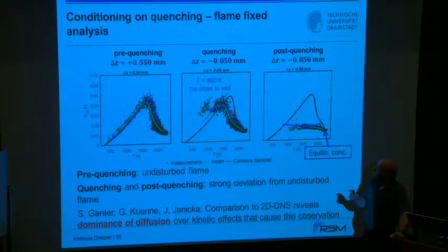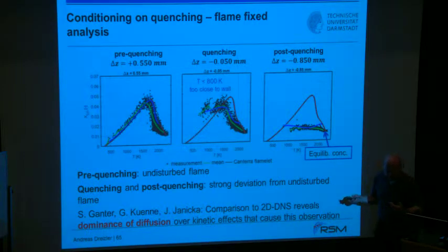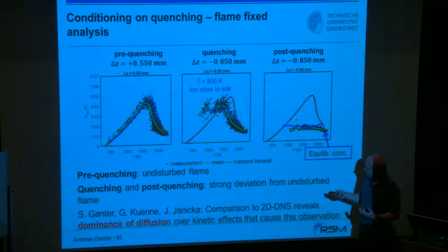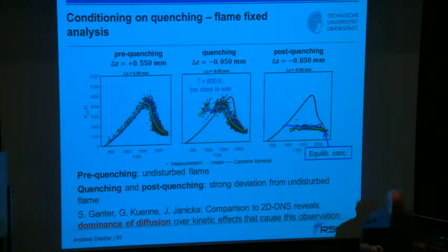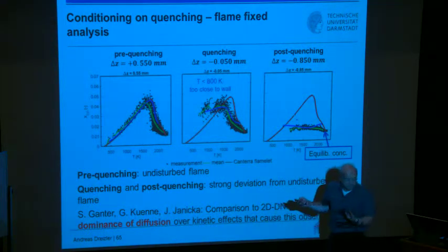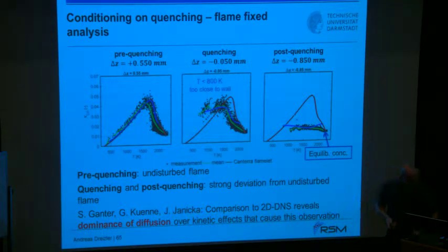It's not the chemical kinetics. Yeah, it's not that the heat transfer by cooling down the gas samples and thereby has an impact on the chemical kinetics. This is the main reason for this fuel. Because you would maybe assume that if you have, let's say, everything cooled down to 1000 K, that then low temperature chemistry kicks in. It does not for methane air. It's not expected as well for methane air. If you would go for another fuel, I don't know, maybe then you have as well low temperature chemistry effects kicking in addition to this heat transfer effects.